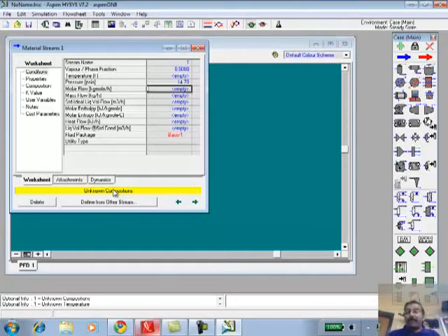Okay, so there are pipeline segments. If you want to track that, go in here, gas pipe, or is it a pipe segment? So you put that in as a model, and only then will it do the calculation. But if I just take a stream and connect it to another stream, it doesn't have any information. It says whatever comes out of this stream goes into the other stream. Okay, good question.